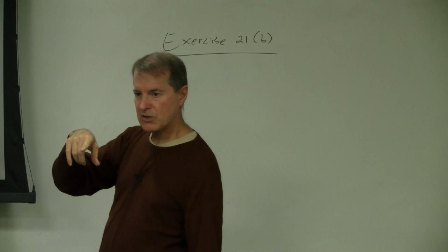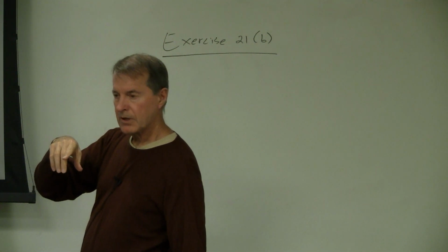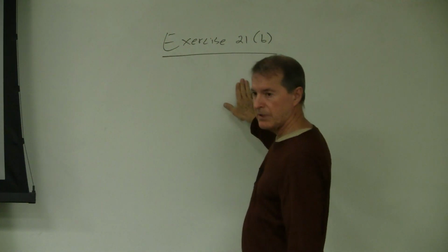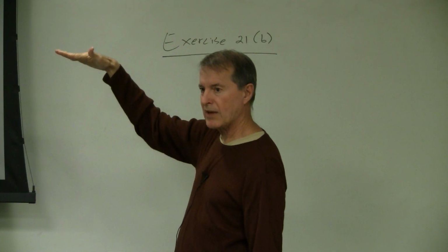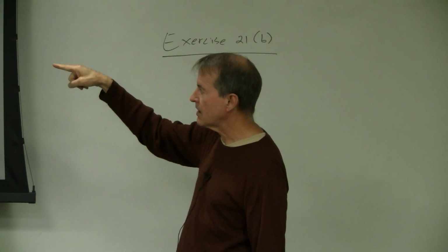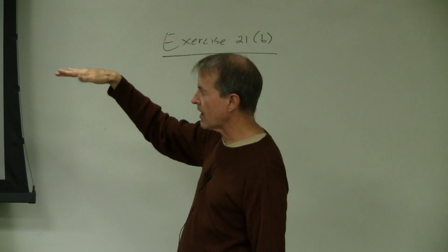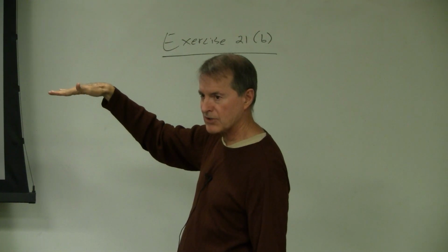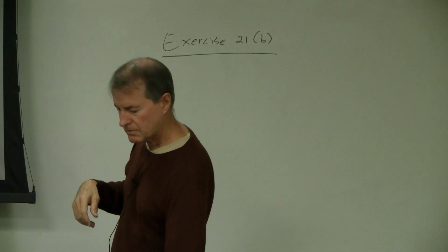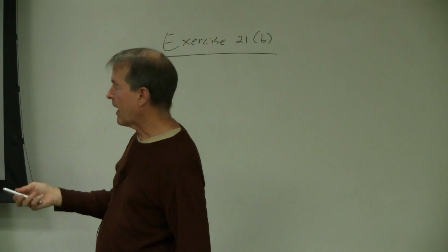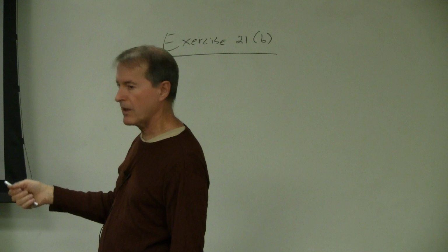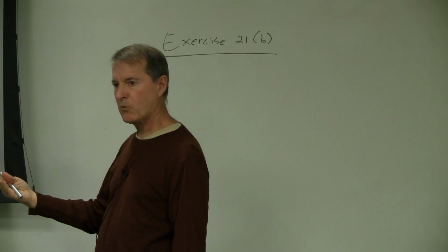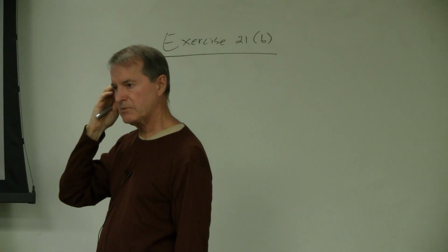So in this particular problem, exercise 21B, you were able to write this down, because this figure right here on this slide is the key to analyzing partial address decoding. How were you able to identify a column that would make one of the devices uniquely identifiable?